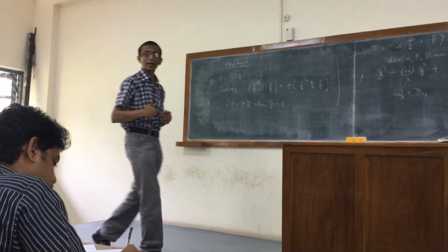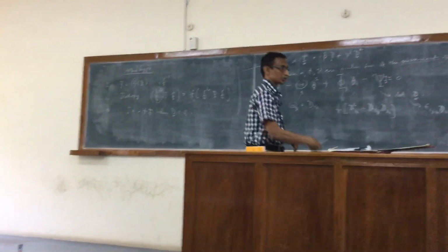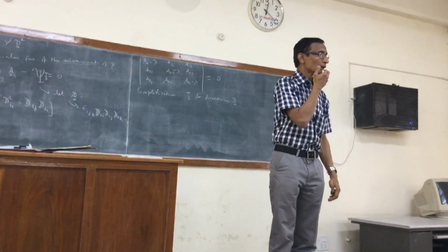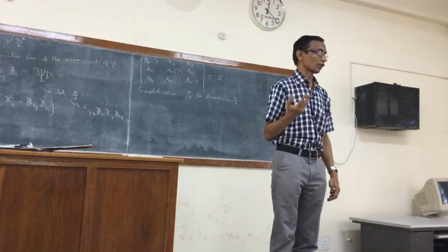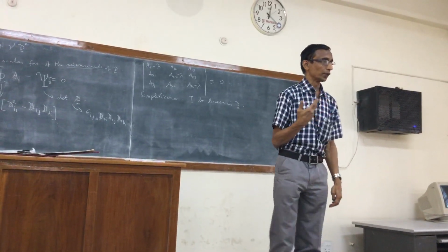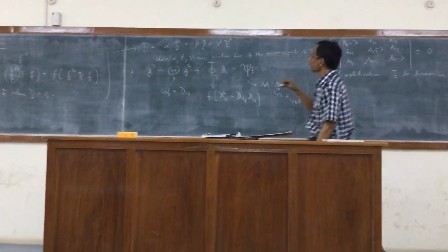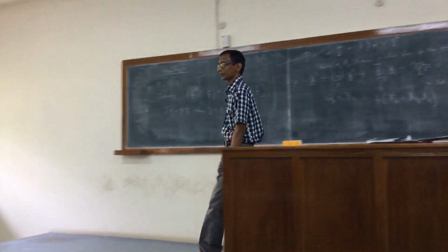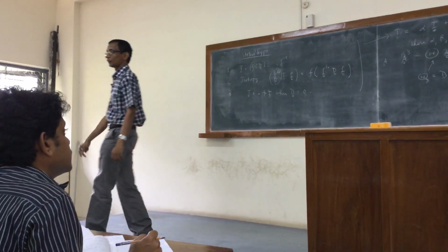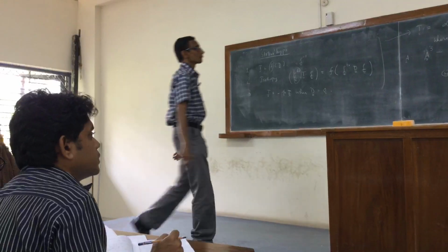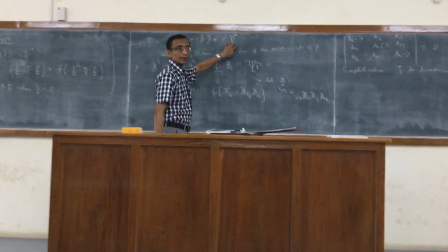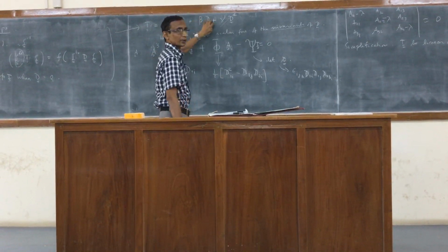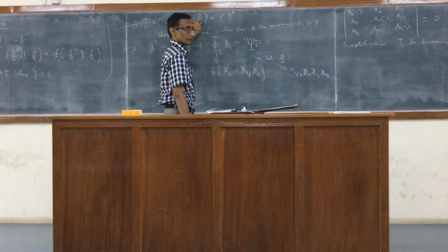So consider a simpler class of fluids for which T is linear in D. This will lead to the very well known linearly viscous fluid, or what is often referred to as a Newtonian fluid. Now, if I impose that, clearly this term would vanish automatically. Even if gamma is a constant, it can be a function of the invariants, right? D squared we cannot have because it's linear in D, so this will automatically vanish. So we are left with these two terms, right?